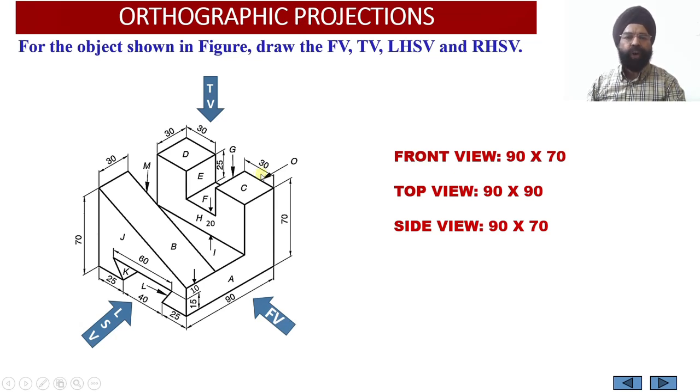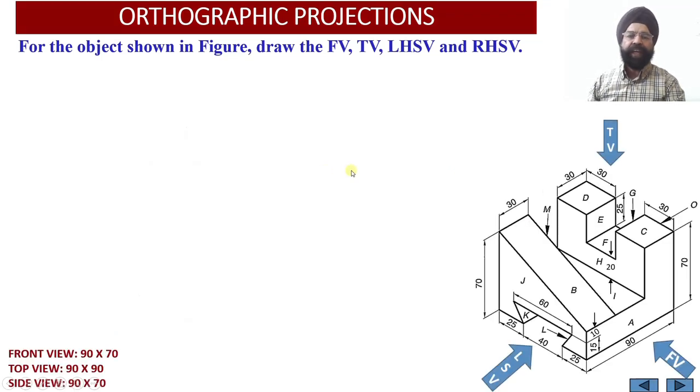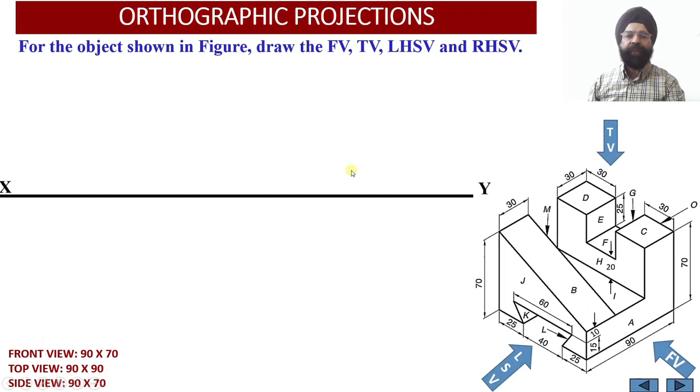So this will be drawn dark onto the profile plane, while certain portion of the surface J, now it is not this surface J, it is surface J which is lying on the other side of this inclined web, will appear as a dotted line or the covered portion compared to this surface H over here. So with this background, let us start with the construction of the orthographic projection.